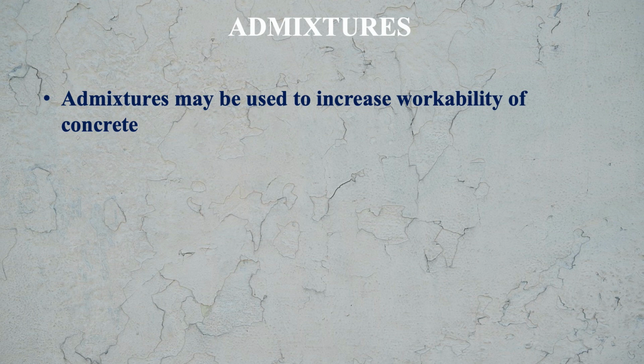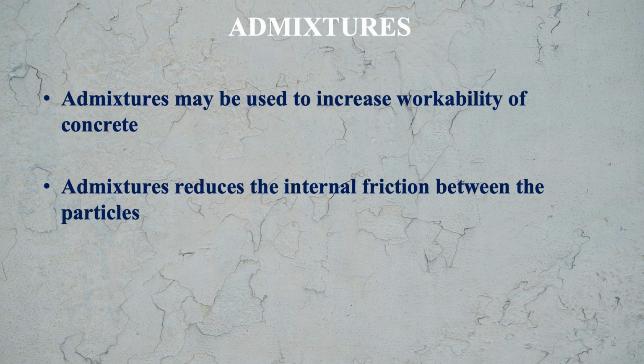Now let us see the effect of admixtures. Admixtures may be used to increase the workability of concrete. What does admixture do? Admixture reduces the internal friction between the particles.